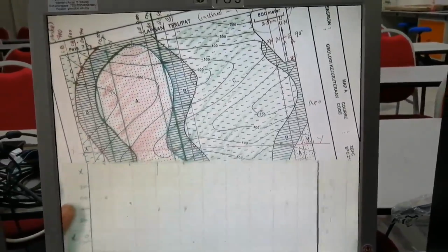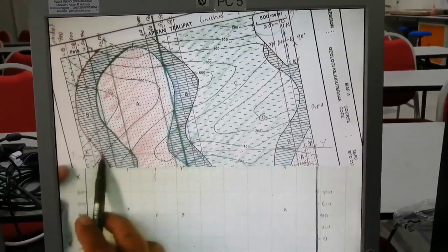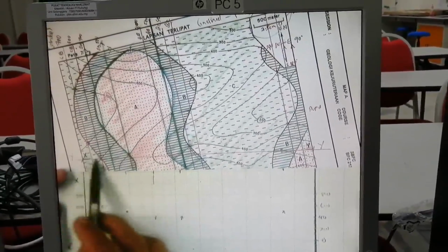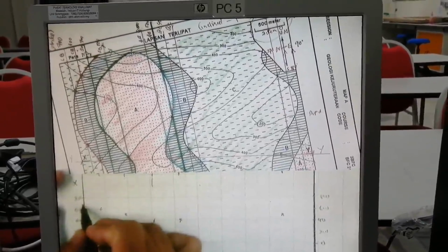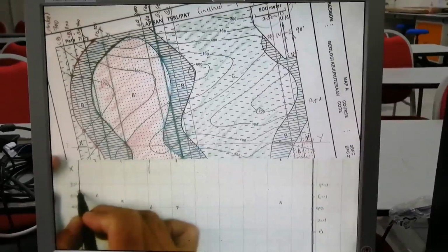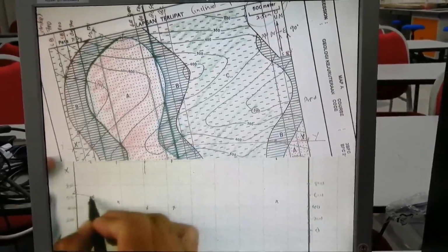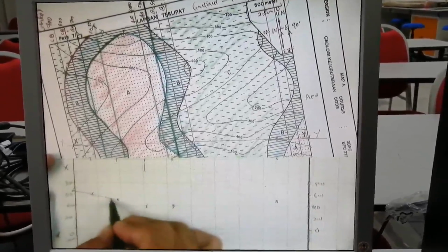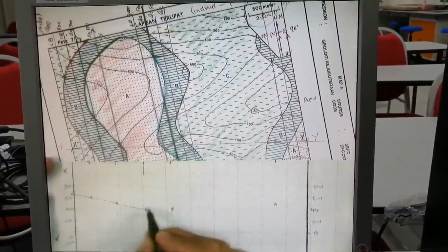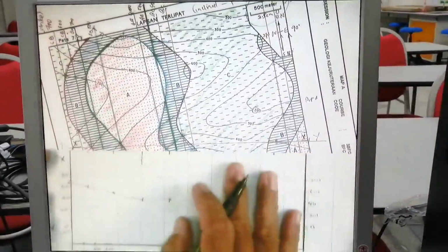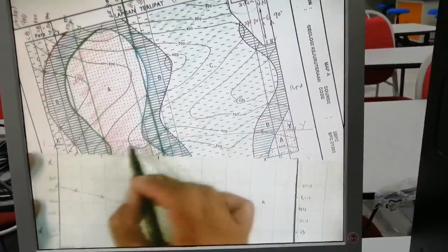We know that. You read again. We have 600 contour height here. We have 700, so that means this area is higher than 600. It's not like this, it must be like this. 700 is somewhere here, so less than 700 must be somewhere here. And then drop easily. Just drop, and then from here to here, is it flat? Looks good. This is referring to this point and this point, 400 and 400.